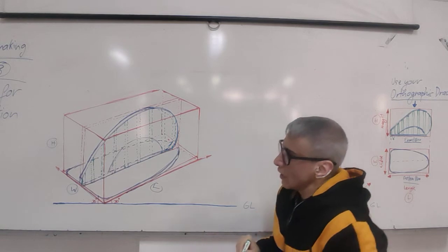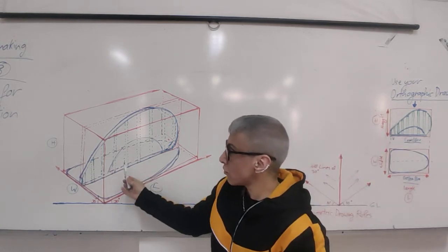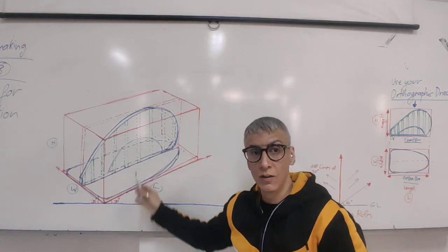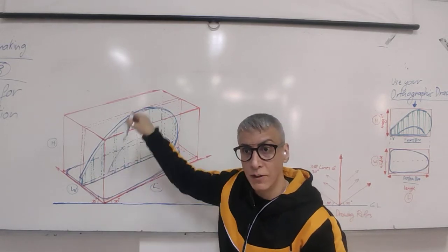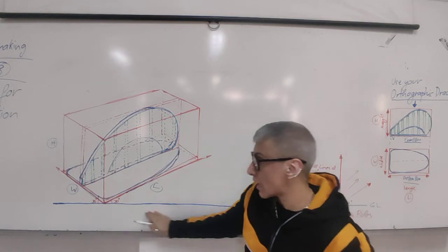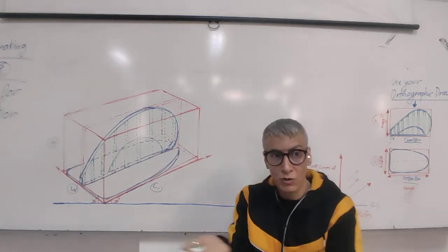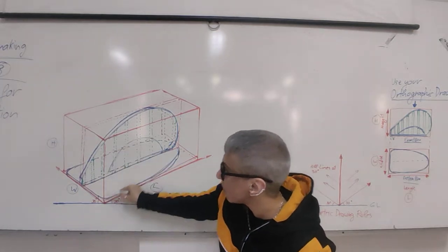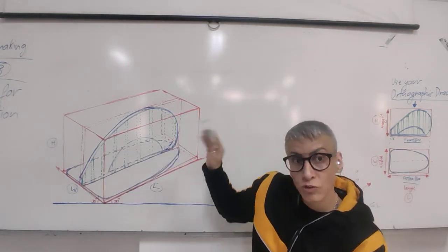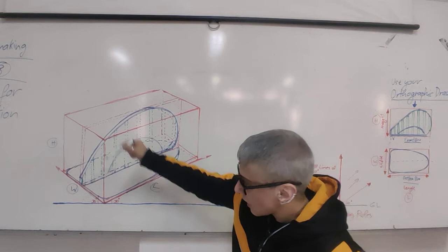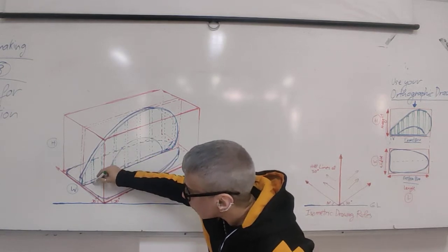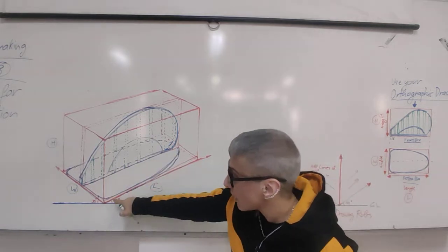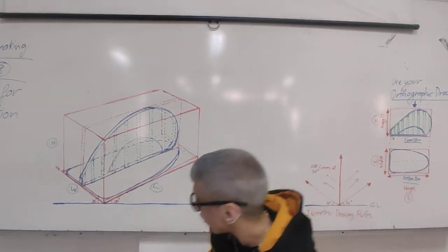Okay. Now, be careful, these lines must be perfectly vertical, perfectly. So, according to the ground line or your page edge, must be 90 degrees, okay? Following exactly these lines. Very important. Don't shift. Now, from each of these lines, we will take other lines going in this direction, touching this curve here.